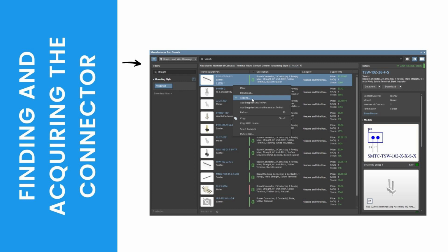Third, click the Filters button to display the filters pane. Fourth, the list of available filters is dynamically updated to suit the category being used and can be quite long. To help manage it, only the most commonly used filters are displayed. Scroll to the bottom of the list and click the Show More Filters link to display all of the available filters. An efficient way of working with the filters is to use the search field at the top of the filters pane. Searching returns strings that match in either the filter name or in the filter settings.